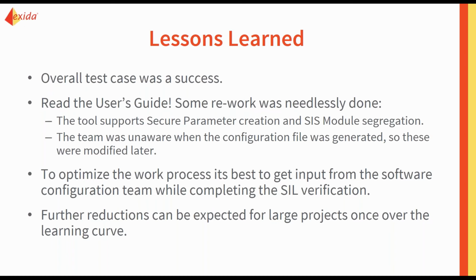In this case, I would say that that 50%, while impressive, could have been cut down even more if you had the application programmer with the design team as they were doing the SIL verification. Another important thing is basically to read the user guide. Those secure parameters that had to be massaged in later are possible to do with the tool. You can do that without having to massage it later.